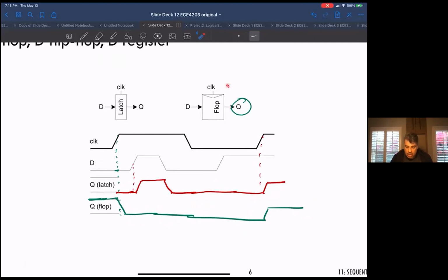The flip-flop is 2 latches back to back. So inevitably it has more timing constraints, there's more of a delay, there's more of a timing overhead associated with a flip-flop, just because there are more circuits, more delay, etc. A latch is a lot simpler, so it can go faster. But the problem with the latch, or anything that's level sensitive like this, if you're going to have a bunch of them in your circuit, invariably one of them will do something you don't want it to do, and you'll miss the problem.